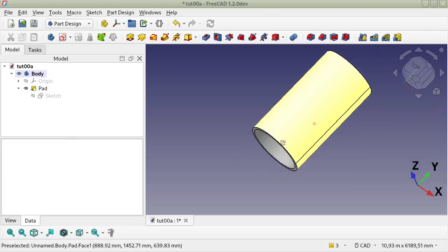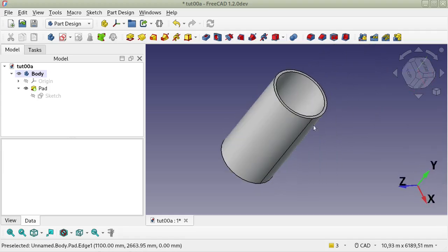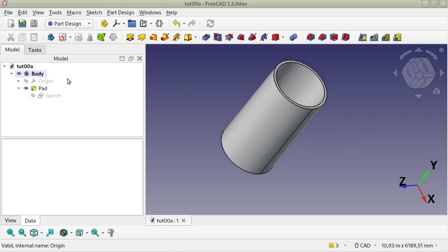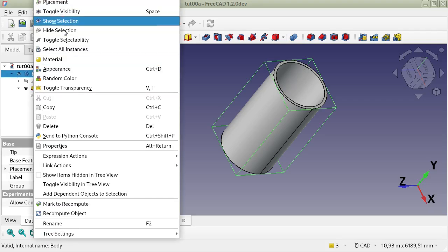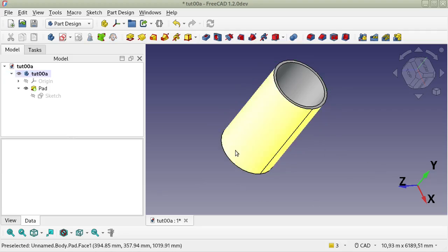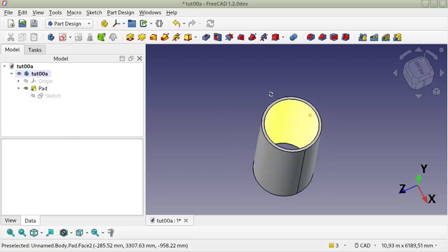So we want to make the tutorial more interesting by using 2 kinds of meshes with tetrahedrons and hexahedrons. The strategy to have hexahedrons is to extrude the part.